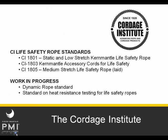In the United States, test methods for static and low-stretch ropes are set by the Cordage Institute. Look for ropes tested to Cordage Institute standard CI 1801 or meeting the requirements of use standards such as NFPA 1983, which refers to CI 1801 as a requirement. Cordage Institute is also working on a dynamic rope standard as well as a standard test method for heat resistance for life safety rope. However, these standards aren't finished yet, and so we won't be able to refer to them.